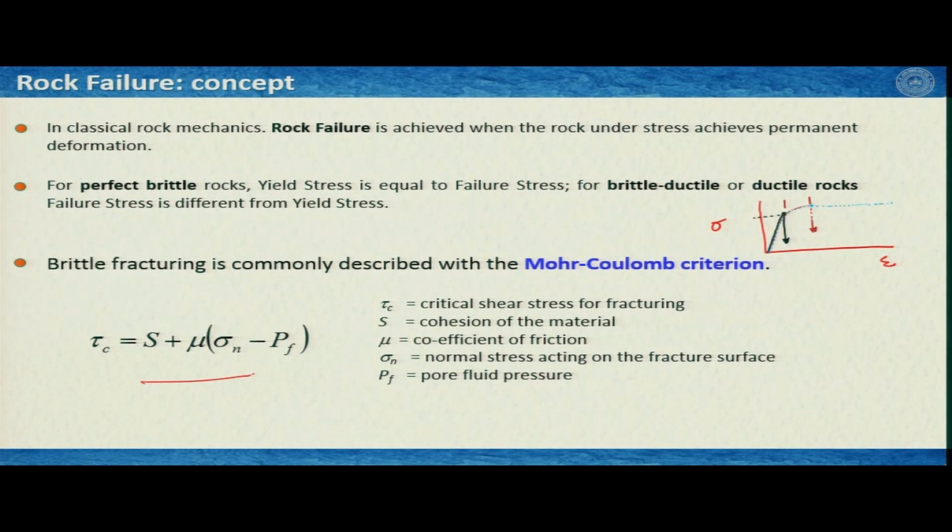And we know from the previous lectures that it can flow at constant stress, then we call it steady state. It can flow at higher stress, then we call it strain hardening, or it can flow at lower stress and then we call it strain softening. So, these are the processes we have learnt, and we can see this more in one of the next lectures when we talk about the stress strain curves.